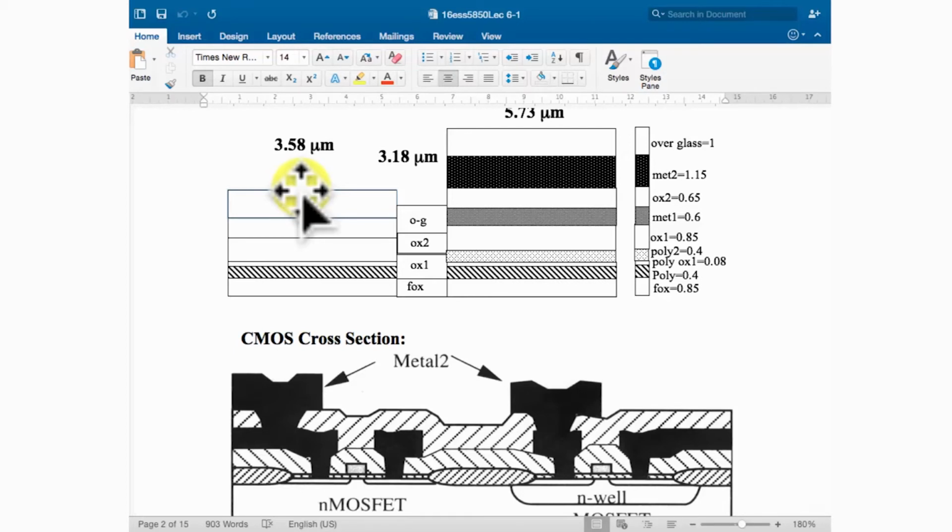So it's not very thick for all purposes. If you want to put a large proof mass underneath this kind of cantilever, sometimes you need to consider using different materials and different structures to put them together. If you want to use only those materials, they are not thick enough. But they are okay for fabrication of the cantilever structure, for thin structures, or bridge or membrane structures.